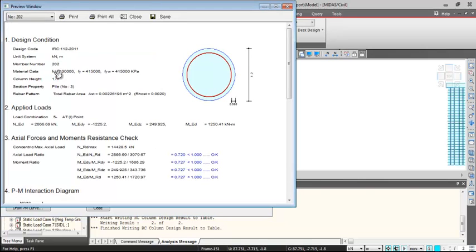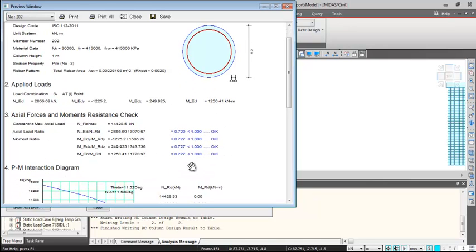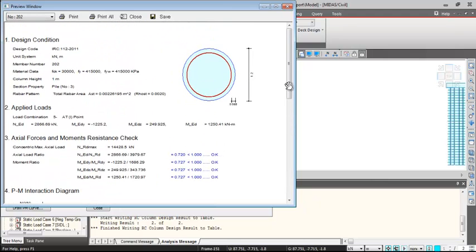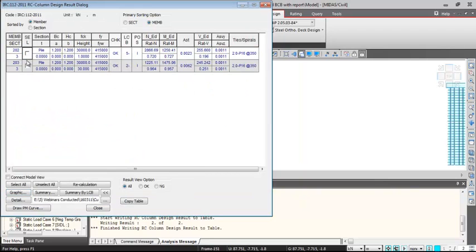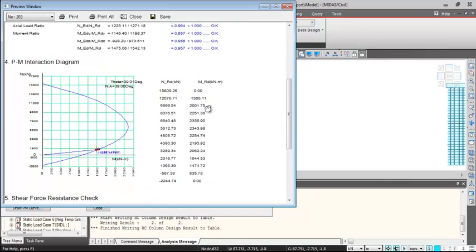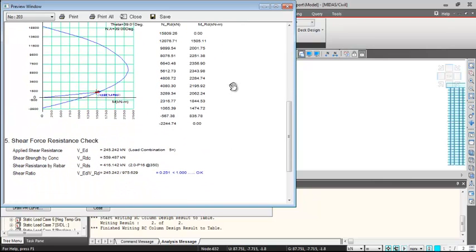See the column height which is considered over here is 1 meter and the factor of safety seems quite high, 0.7. Shear needs no checking. However, when I check element 203, that is on the P2, and I go to graphic, the length considered is 30 meters and look at the acting and the resisting forces. So it is just safe. One means maximum utility and it is utilized up to almost 95-96%. Shear is still not an issue, it's about 25% only.